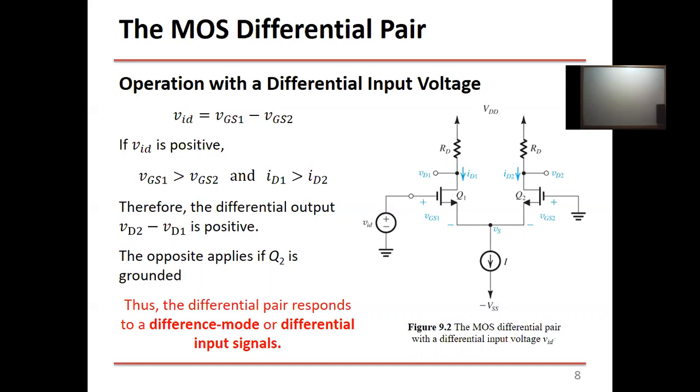So let alone, you remember the coupling capacitors that we used to use? They are in microfarads. So they are 1 million times higher than 1 picofarad, right? So imagine the huge size. So you cannot insert in an integrated circuit a large capacitor in microfarads. This is impossible. So this is why in integrated circuits, we avoid coupling capacitors and these large capacitors. We can add just a very small capacitor if needed in picofarads, that's fine. But you have to know that even this small capacitor will occupy a large area compared to the transistor itself, okay? So these are the two main advantages.